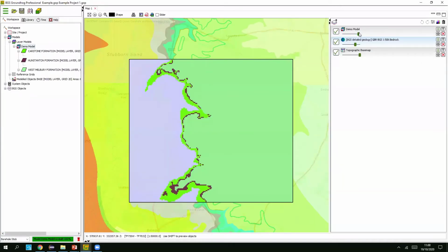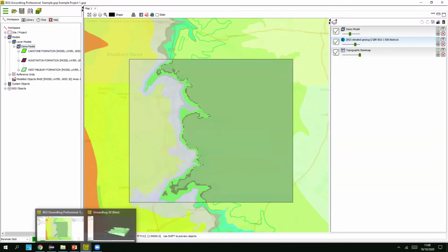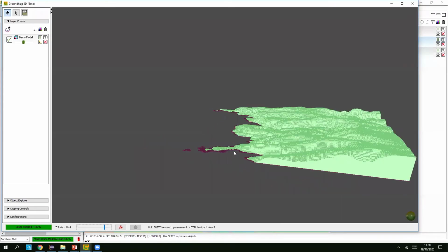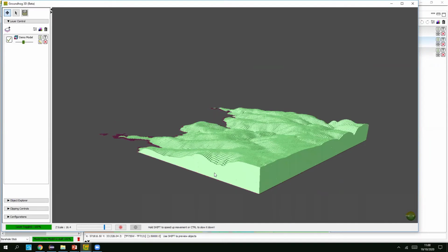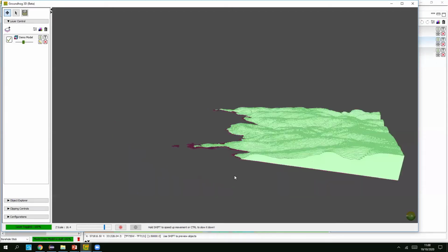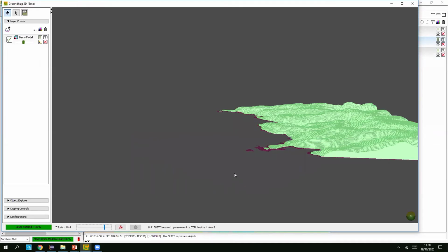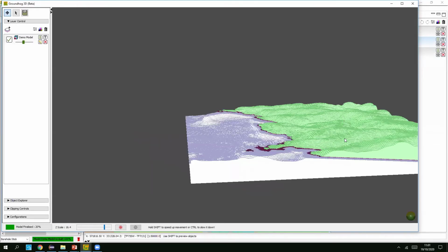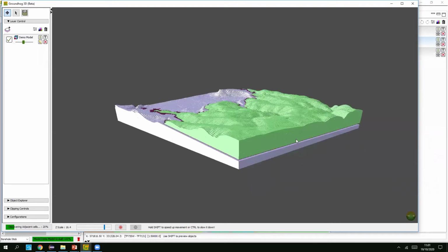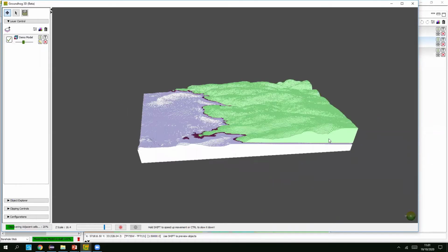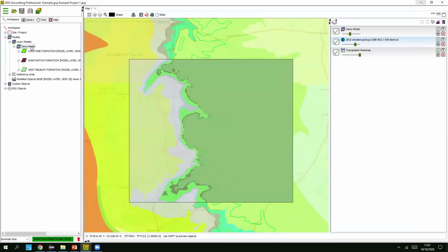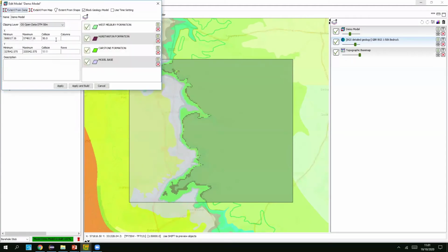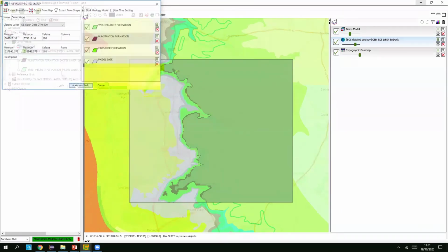So that gives you a first idea of the model building within the software, in terms of how we handle things as a grid-based model with a series of stratigraphic layers. What I'm going to do now is I think I might clear down the session, maybe just clear down the model, build a new model, and we're going to work from data inputs instead. So let's just rebuild that at a low resolution for speed again. So let's go back to 100 and rebuild.